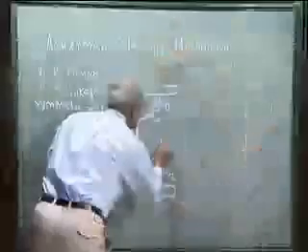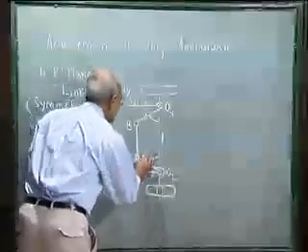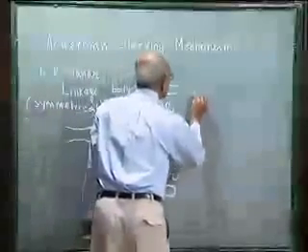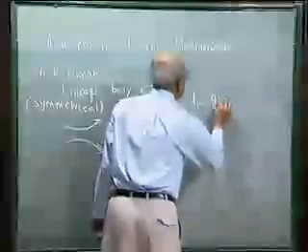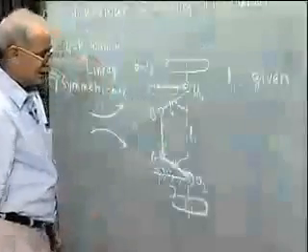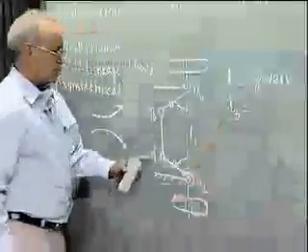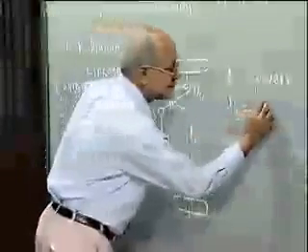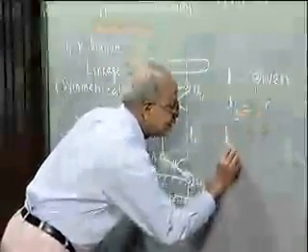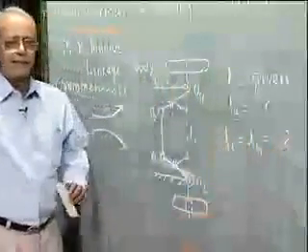So what we see is that this 4R linkage has 4 link lengths. Say L1 is the fixed link length, which is given, that is decided by the location of these two pivots O2 and O4 on the body of the automobile. Then L3 is the coupler length, which we have to find out, and L2 is the same as L4, and we also have to determine this link length for a proper steering action.